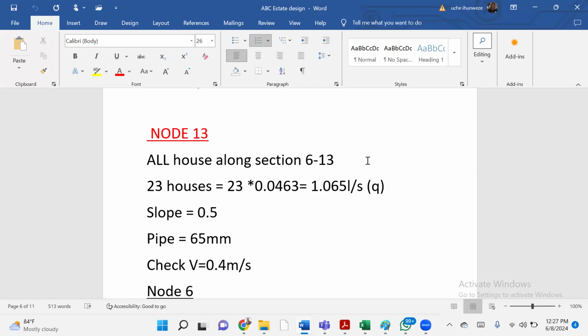We already assumed 0.5 before, but I've changed it now so you don't copy. Assume a slope of 0.1 and 30 persons per house, not 10 persons per house. So it's like a duplex or a high rise. I'll put it on the WhatsApp group: 0.1% and 30 persons per house. Please get me the pipe sizes from 1 to 30.